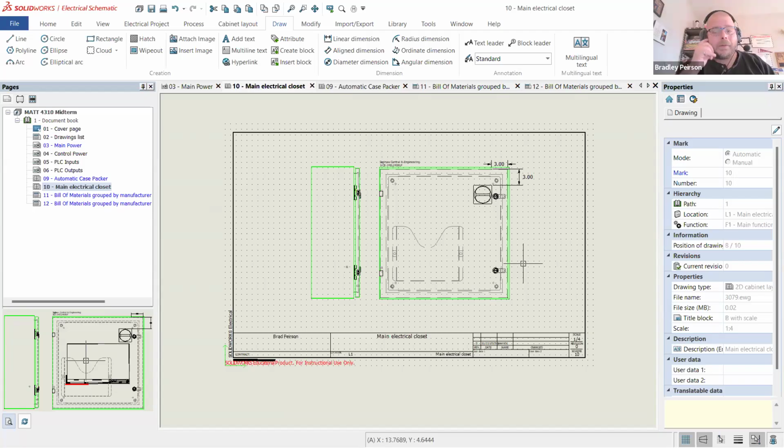In some companies, such as Rittal, they sell them together and don't have a separate part number for the backplane. That becomes a time where we have to bring in just the cabinet part number and then cheat with the Phantom in order to get a backplane in. Because if it's all one part, I can't put in a cabinet and a backplane. It doesn't work. So the Phantom trick is a key takeaway from this video.